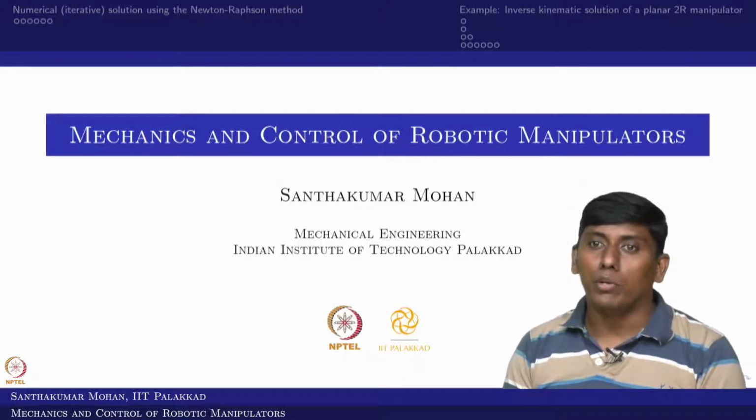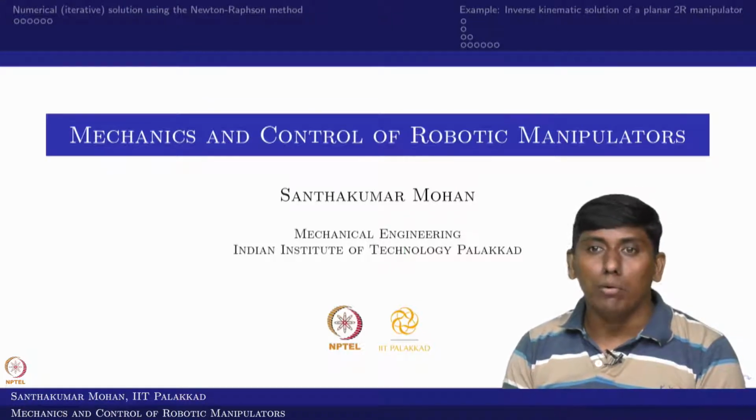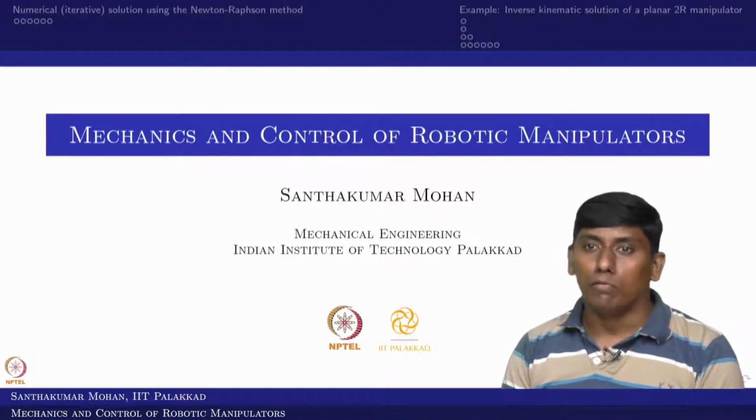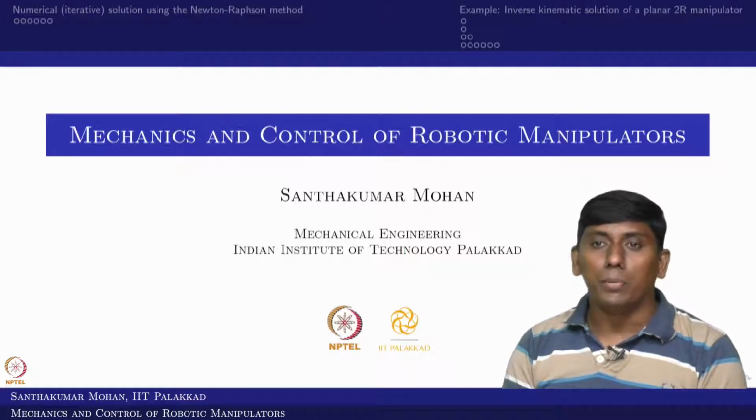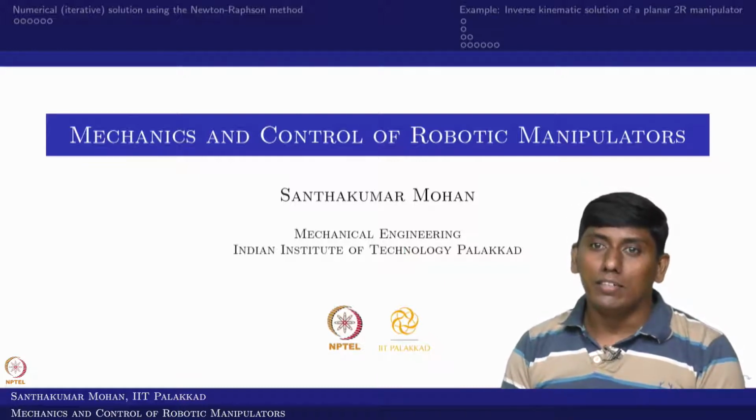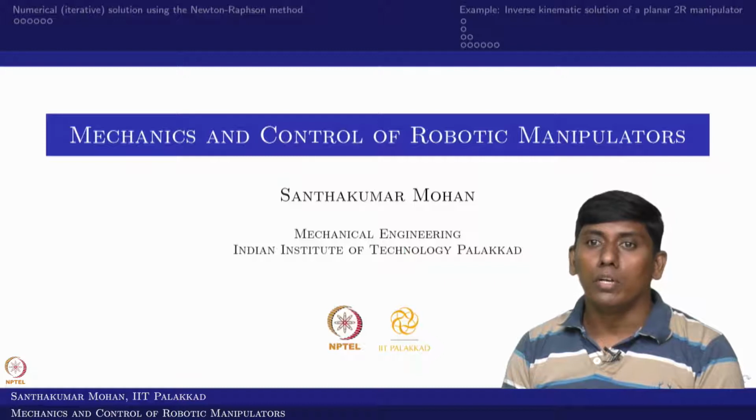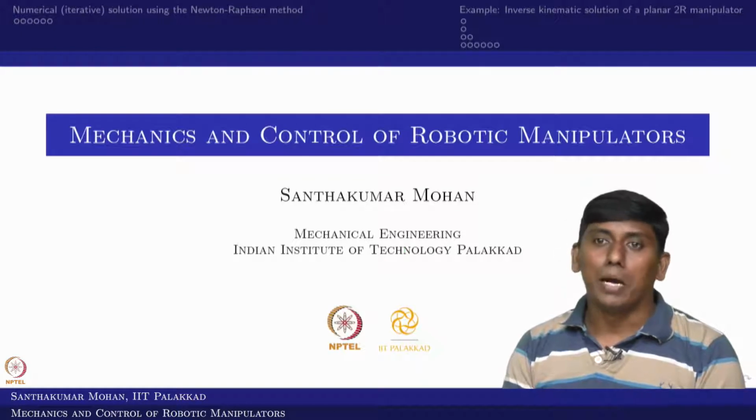That would be beneficial when you do online programming and other things. For example, you have a robot in real time. So, obviously, the numerical method would be a little more beneficial than the closed form solution from a computational perspective. So, this particular lecture is going to talk about how to use the Newton-Raphson method for finding the inverse kinematic solution of a serial manipulator.